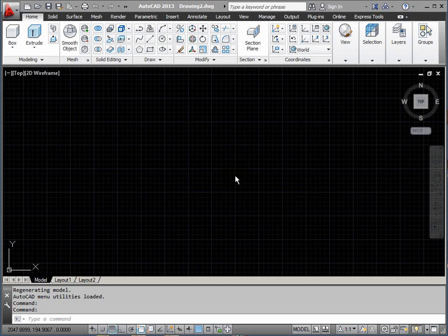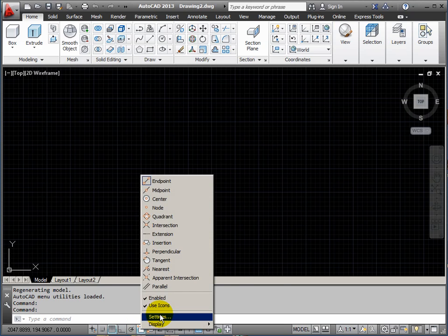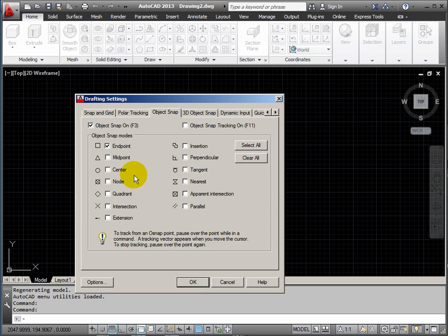Hi, this is another AutoCAD tutorial looking specifically at controlling the UCS and orientating yourself around a simple shape. So I'm going to start off, I'm going to keep the grid on in this view and having a look at the object snaps. Don't need many here. Endpoint primarily, and we'll use a midpoint later on, but just endpoint will do for this.